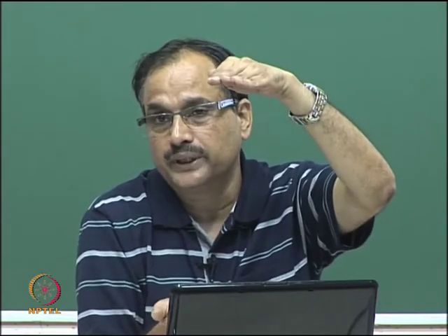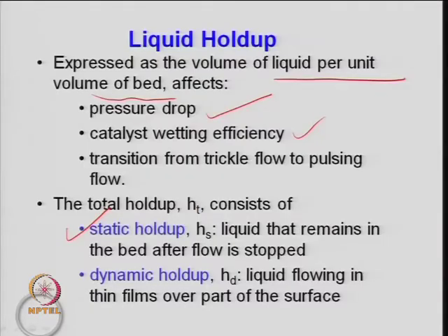When the liquid flows continuously, something is going in and something is coming out continuously. But this is the liquid which remains in the void spaces between the solids. That is known as the static liquid hold up. How to measure that? It is the liquid which remains in the bed after the flow is stopped. So, one can measure it. At different liquid flow rates you will have different hold up, till it reaches some saturation volume.